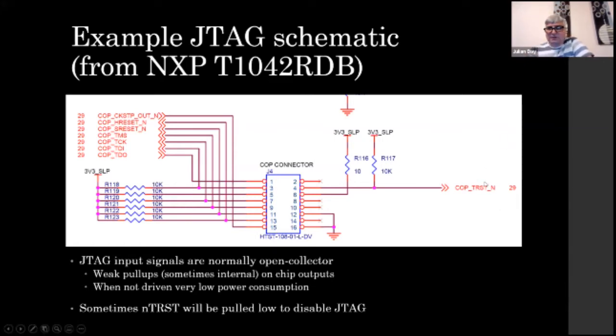There's also an additional pin here, which I mentioned, which is kind of optional in the JTAG standard, your test reset pin. And this, as it says, resets the JTAG TAP controller, test access port controller, on the device. And again, you'll often see this pulled low instead of pulled high to disable JTAG functionality, because it's intended for test. So in a production board, you don't want it to be accidentally enabled. Again, that can cause you problems for aftermarket devices if you're trying to retrofit a JTAG connection.